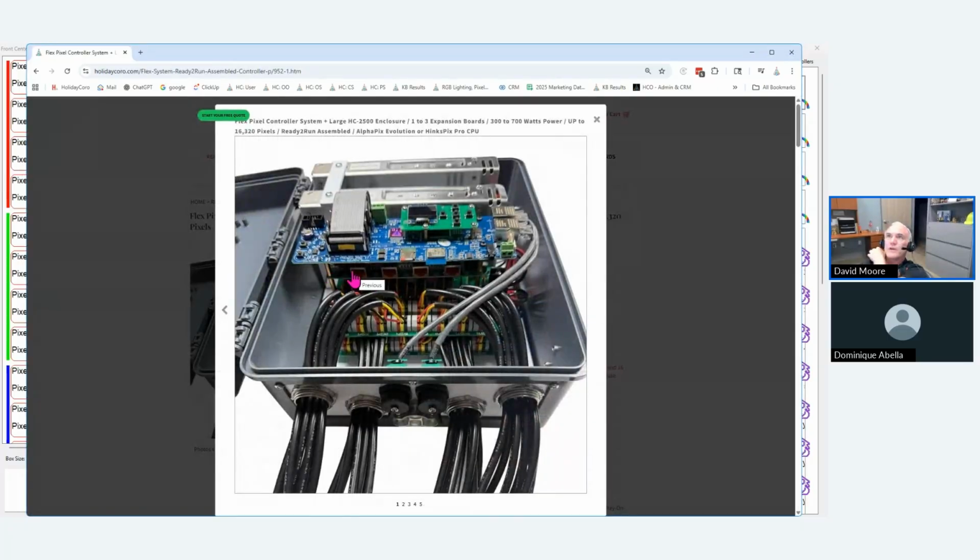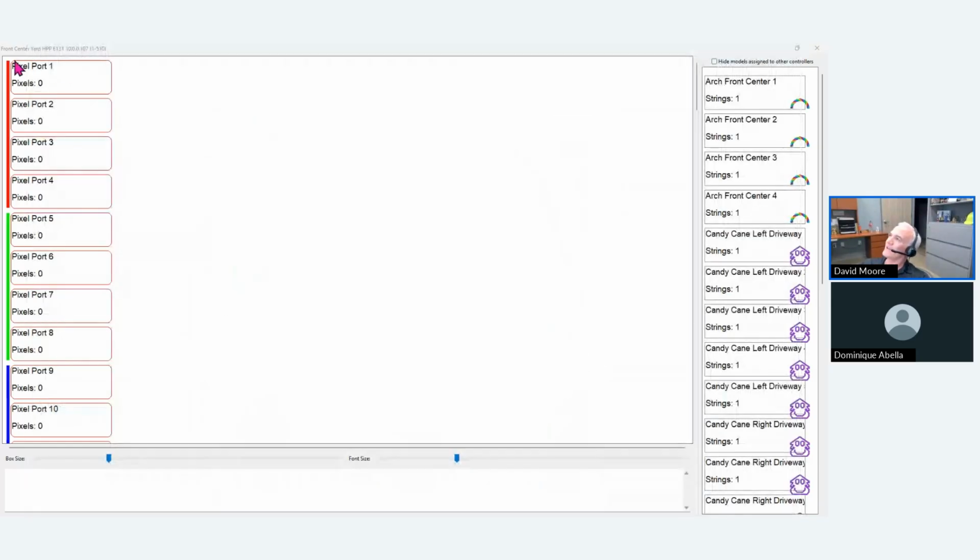So in our configuration, we're going to have 1 through 16. So this is 1, 2, 3, 4 on the furthest left jack, 5, 6, 7, 8, 9, 10, 11, 12, 13, 14, 15, 16. Why is that? It's because a Cat5 cable has 8 wires in it. Paired together, because we need 2 wires to send long-range data, we have 4 pairs of wires. And we have 4 ports, 1 port per pair of wires. That's why they're grouped together. So when xLights is showing you that little block around the red, that's telling you, hey, this is a block of outputs right here. All right, so that is the first port.